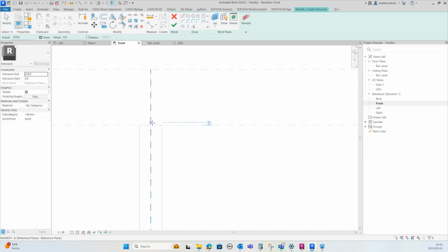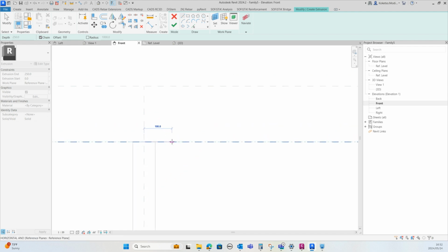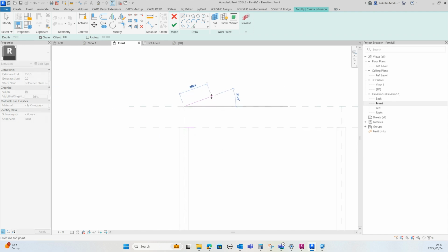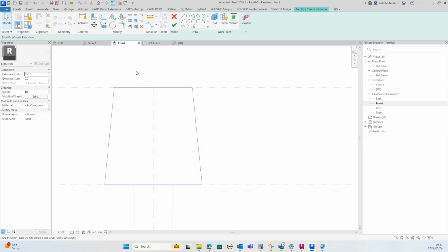So from there, you're gonna place your point from this. You're gonna use this as your insertion point, and then you're gonna drag your mouse to the right at 100 millimeters, and then you're gonna go to the top on this insertion point. Remember, we're gonna use the 200 millimeter thickness, and then from there you're gonna take it to the right at 80 millimeters, and then diagonally towards this point. So you're gonna select these lines, say mirror plate axis, and then they're gonna be copied to the other side.